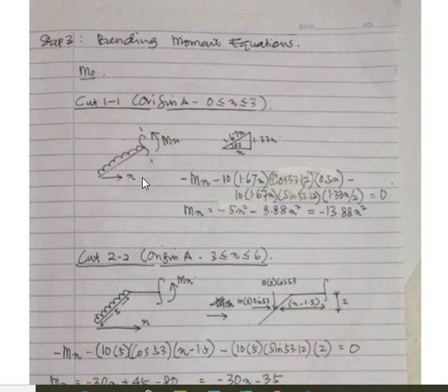Okay. Next, when you do cutting number 1, Mx is a balancing moment. After you do the cutting, you have one load only on your system, which is the inclined UDL, 10 kilonewton per meter. Since you consider this as your X, to make our calculation easy, I determine the relationship for this triangle.